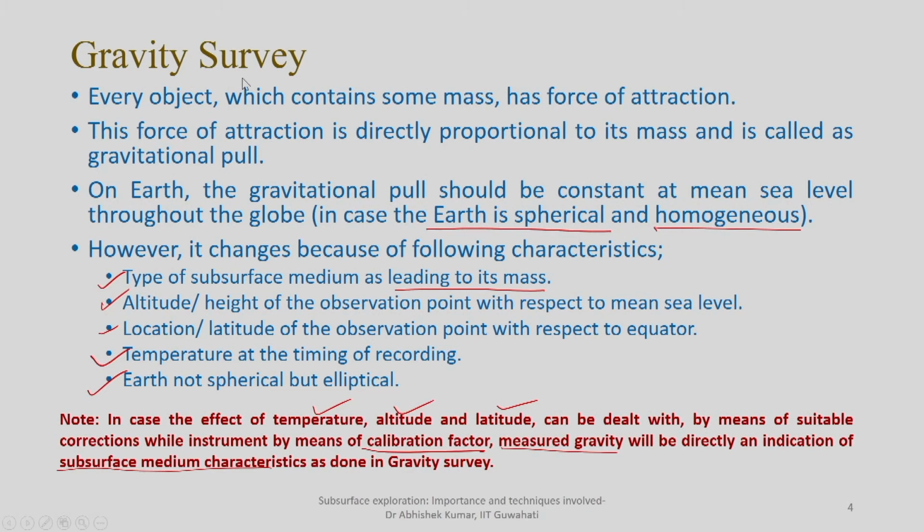Even sometimes plate corrections are also required because of some additional material which is available between the bedrock and the ground surface. And once you apply all those corrections, you will get an idea about how much is the actual value of gravity. If you take the difference of this actual gravity with respect to the generalized value of gravity, that will possibly be an indication that there is stiffer material or lighter material within the ground medium, which is a possible indication of change in medium characteristics, and that is how you target for understanding in the gravity survey.